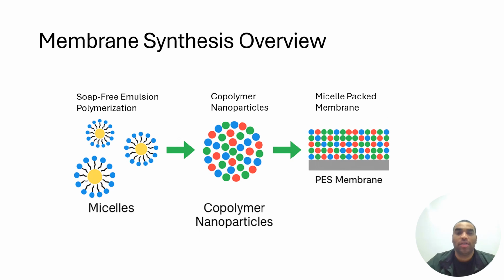This process begins with the goal of synthesizing a nanofiltration membrane using a soap-free emulsion method to pack amphiphilic random copolymer nanoparticles. Unlike traditional emulsion polymerization, this method avoids surfactants, which reduces contamination and improves membrane compatibility for biological applications.